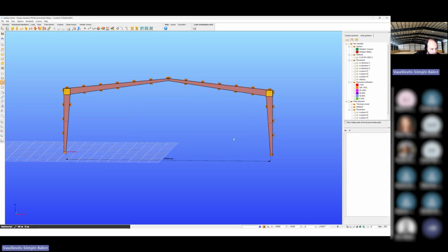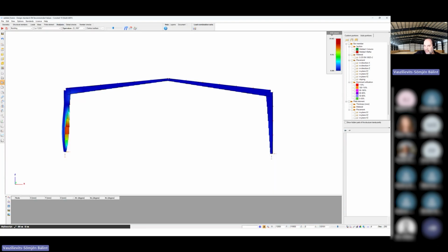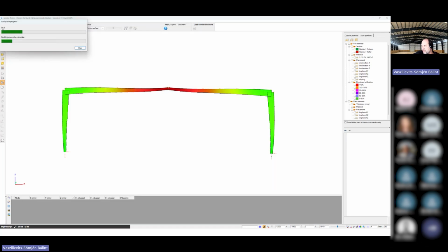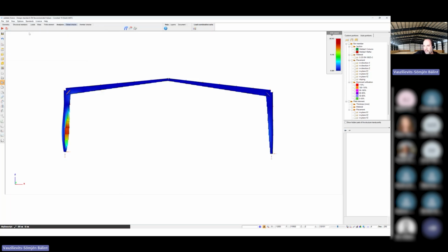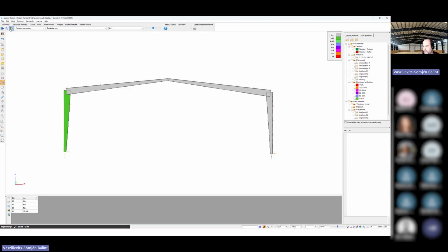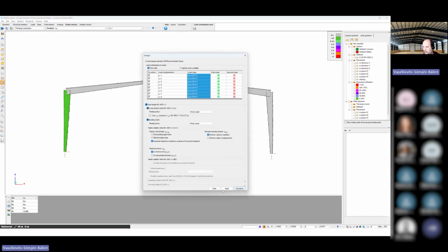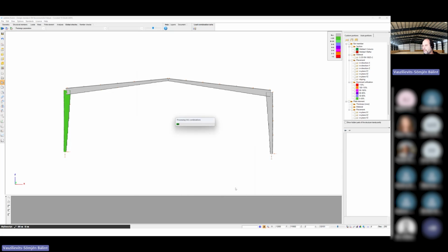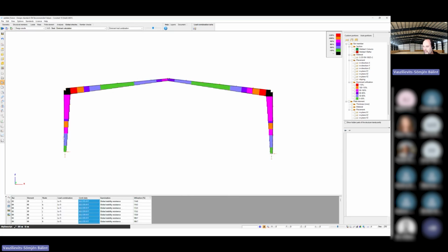And then maybe also, yeah, maybe it will be enough. Let's see what happens. It's still important that all the analysis is first order, and I haven't done anything for in-plane yet. So that's still important to remember, it still needs to be done. So now I run the calculation, still first order only, buckling calculations, and when I run it, I will see that now my column is more or less fine. There is still a part here where the section is not appropriate.